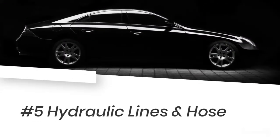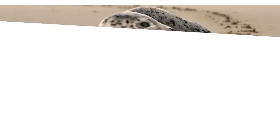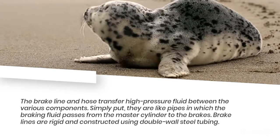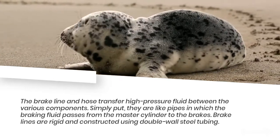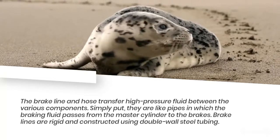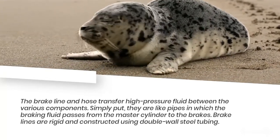Number 5. Hydraulic lines and hose. The brake line and hose transfer high-pressure fluid between the various components. Simply put, they are like pipes in which the braking fluid passes from the master cylinder to the brakes. Brake lines are rigid and constructed using double-wall steel tubing.